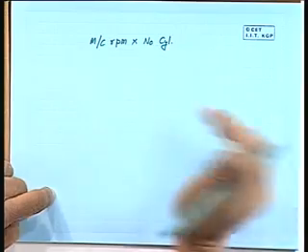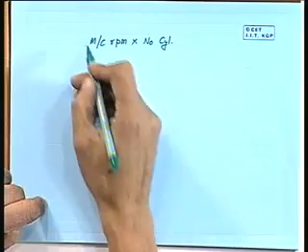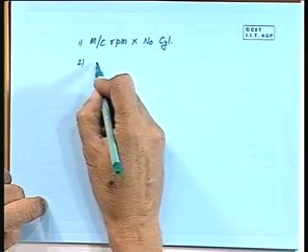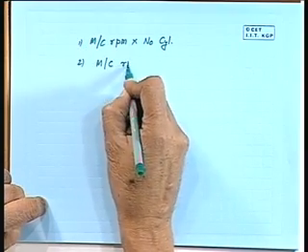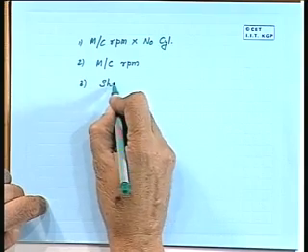Okay. Now, in the machinery you have machine RPM into number of cylinders, which is one sort of an excitation force. One particular frequency is this. Second one is machine RPM. Third, I will say, is the shaft RPM.